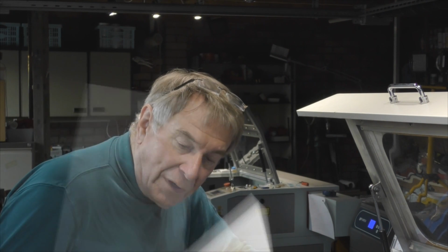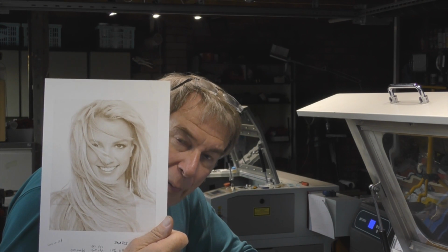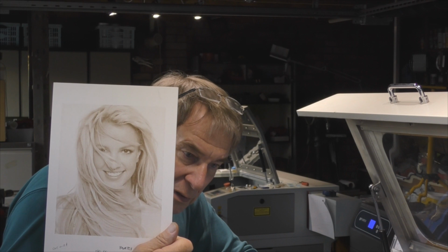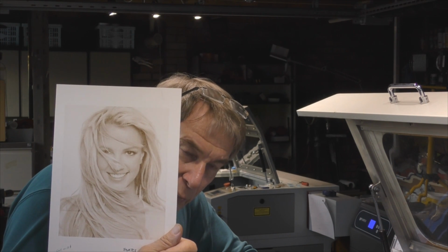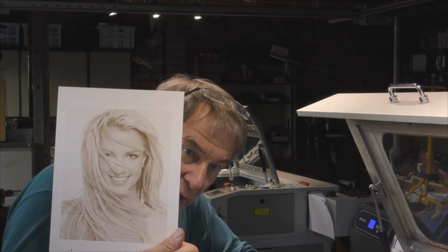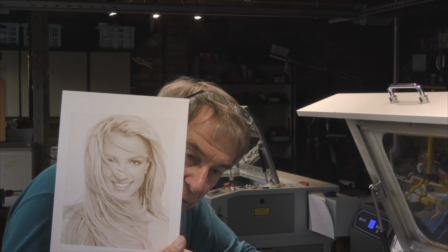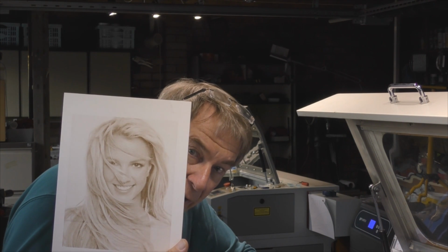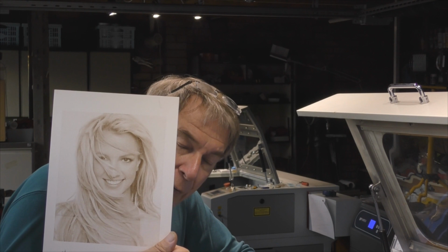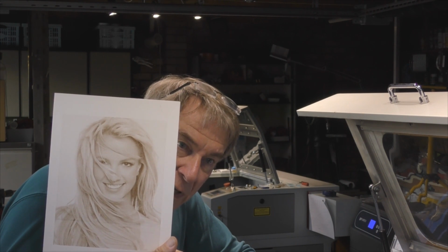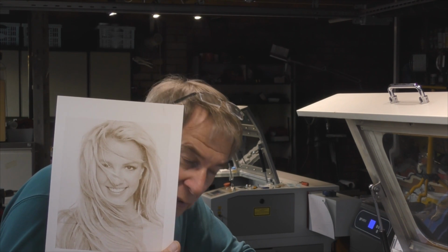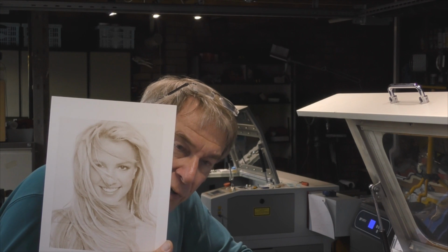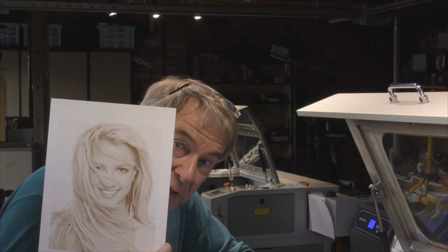You have to have a specially prepared picture for 3D engraving. The whites stay near the surface and the blacks cut deep. Now, just as an example, her eyes, you don't want her eyes to disappear into the background. Her eyes are in the foreground. But that won't happen with 3D engraving. If it's black, it will be deep. So just remember that when you look at a photograph and think, I'll have a go at 3D engraving that.